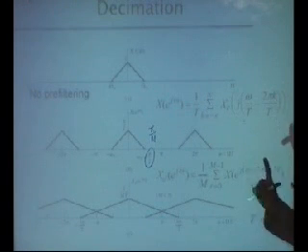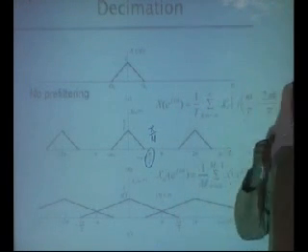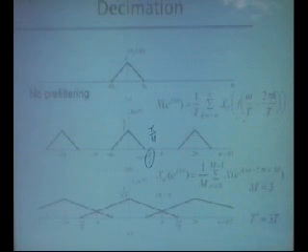It goes 2 ways. One is, knowing the highest digital frequency, you can figure out the m, that how many samples can I easily throw away. This is one way, that you find out your digital spectrum and you say my highest digital frequency is not really greater than pi over 6. So you say it means I am keeping a lot more than what is required.